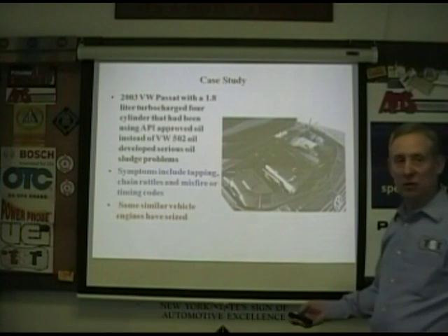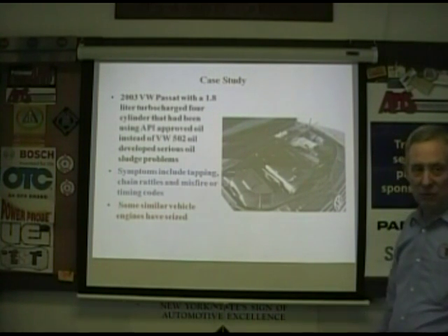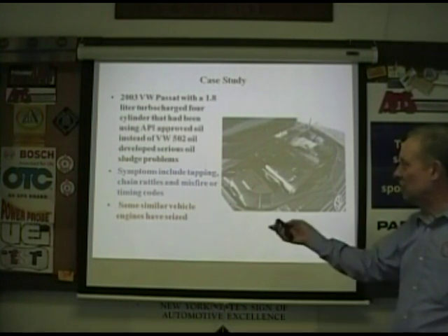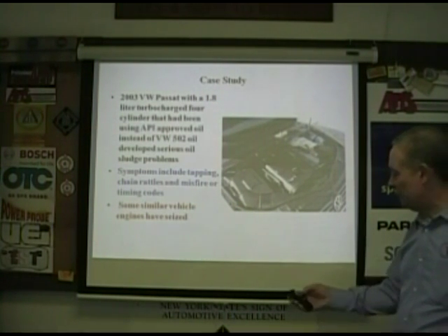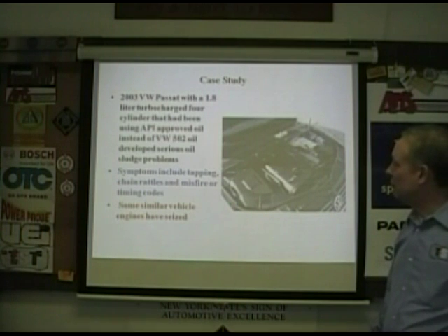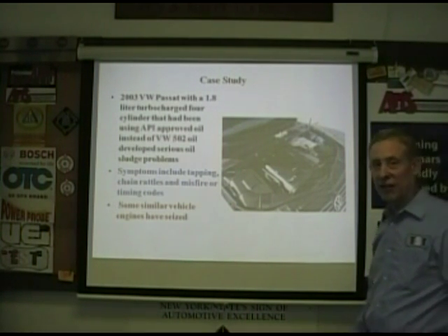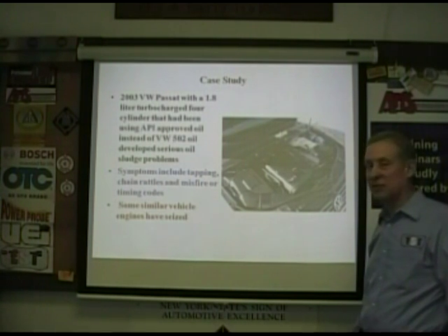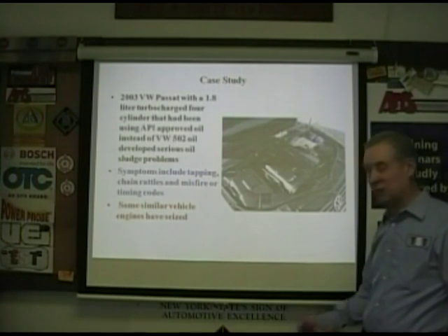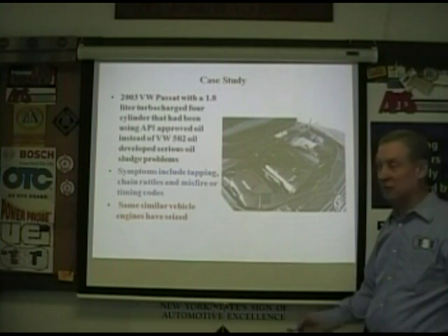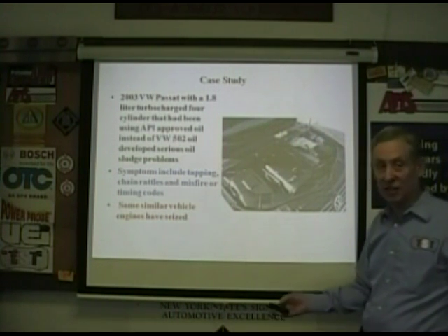Well, I think you were telling a story one time that some of the Volkswagens are experiencing a lot of CAT codes. We're getting a lot of CAT codes. I don't think we're getting so many from this. We're getting a lot from problems with misfire. They've had a lot of ignition coil issues. They've had a lot of oxy sensors that don't get changed till it's way too late. And they've had some issues with the actual CAT itself.